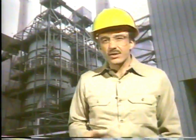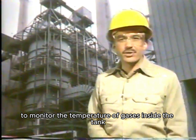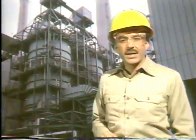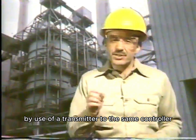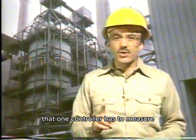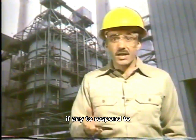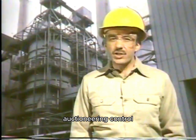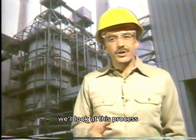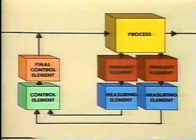For example, the large tank behind me has 3 temperature sensors to monitor the temperature of gases inside the tank. Now, each of the 3 sensors provides a signal by use of a transmitter to the same controller. That one controller has to measure each of the 3 signals and determine which of the signals, if any, to respond to. Now, this type of control loop is called auctioneering control. We'll look at this process and its control loop in a few minutes. But first, let's find out what auctioneering control is about.